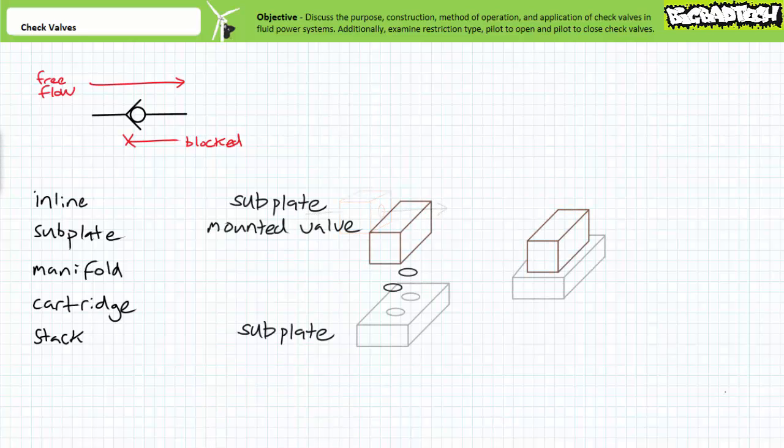In contrast, a subplate-mounted valve uses a machined subplate directly attached to system plumbing, and the valve is then attached to the subplate with threaded connections. O-rings and/or gaskets prevent leaks between the matching valve and subplate ports. Standardized size of subplates and valves allow quick interchangeability.